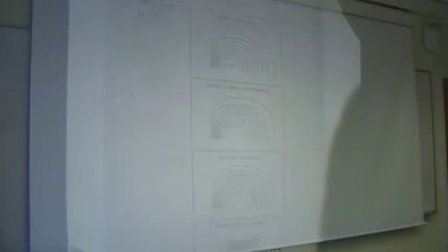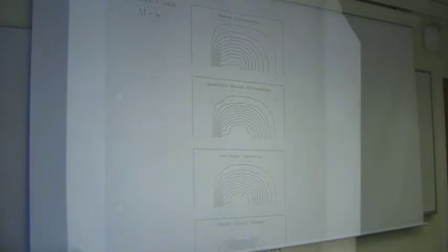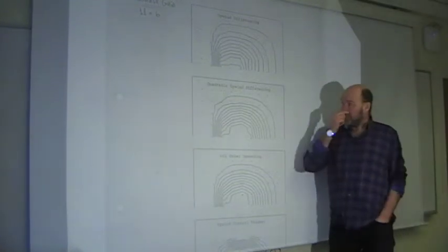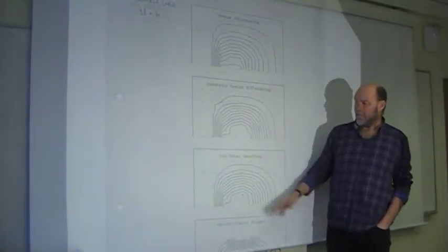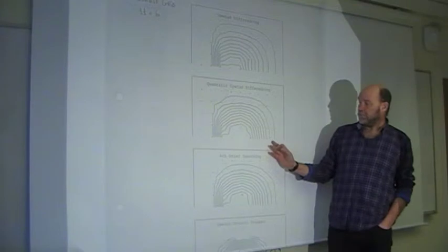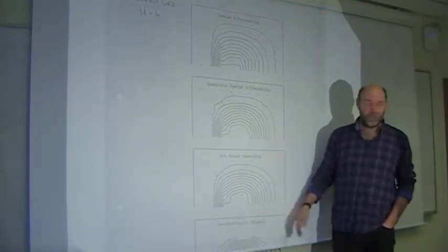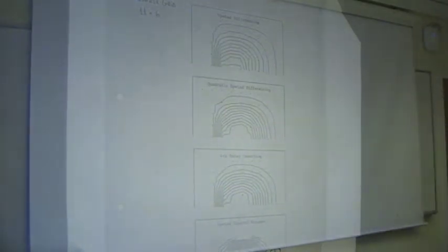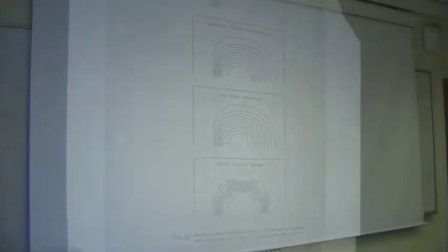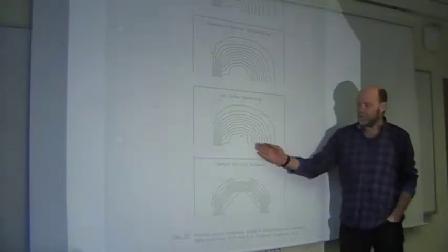And then they play around with even higher order upwind schemes. Quadratic upwind, it really doesn't help much. Fourth order upwind doesn't help. So it's a hard test case, of course, even with so few cells like this, but still almost impossible to get this one correct.